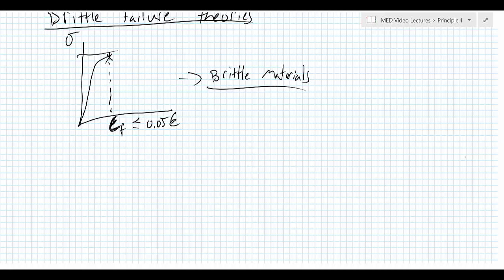So brittle failures are usually significantly more severe than ductile failures, in the sense that if you imagine standing on ice and it cracks and gives way, it can be very immediate. Brittle failures often have much higher significance than ductile failures, because if something fails in a ductile way, usually it changes shape slightly and may even gain some strain hardening. And so the thing itself may fail in the sense that it no longer works, but it won't completely give way.